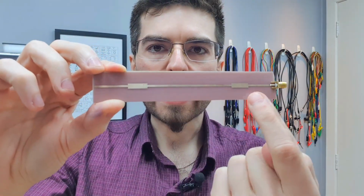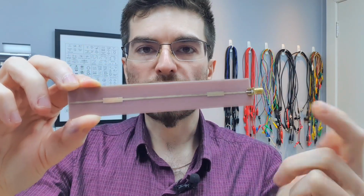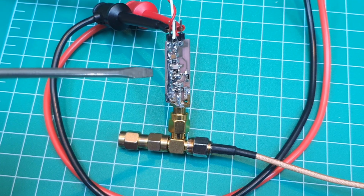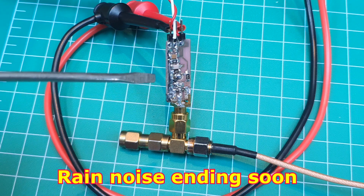When traveling back, both reflected signals will pass through the connector. So the effect of the connector is equal for both pulses, and in some way we are canceling the effect of the connection. To generate the very fast pulse, we are going to use a BJT transistor working in avalanche mode.